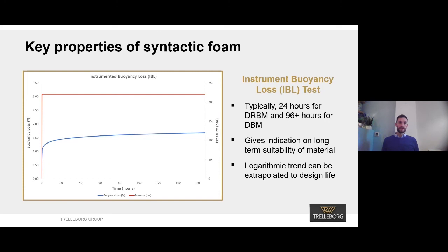The long-term properties of the material can be extrapolated through a logarithmic trend, and that allows us to understand the buoyancy loss of the material at the end of the service life.